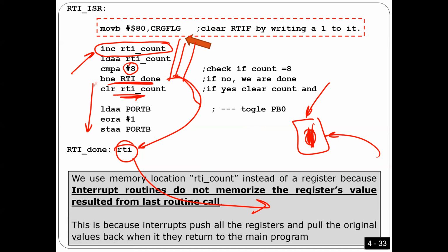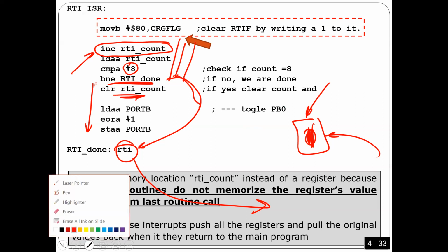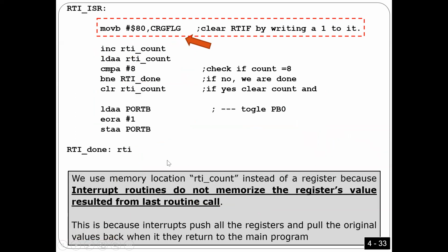So what I'm saying, look here, how it is very easy. All you have to do, guys, is that if you want this program to make a flashing every 1 second, and I just change this number to 4, that means I'm going to flip the LED every 4 interrupts, with half a second. Very simple. If I make this one 16, it's going to be every 2 seconds, and so on. 24, 32, whatever, any number here. Is that easy, right? Any questions?